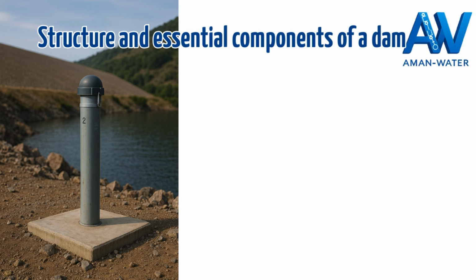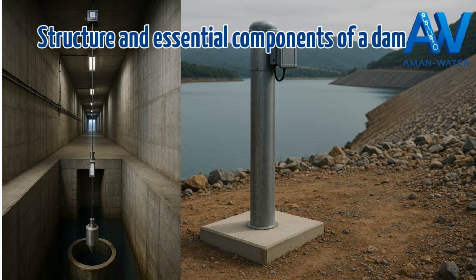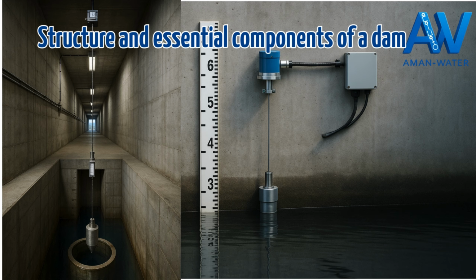Finally, a modern dam is equipped with complete instrumentation. Piezometers measure water pressure in the ground. Inclinometers monitor movements. Pendulums detect deformations. Sensors record water level variations. Everything is monitored continuously to detect the slightest sign of weakness. Now that the structure is established, the internal components are in place, and monitoring is ensured, one central question remains.